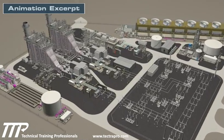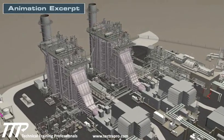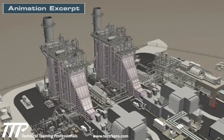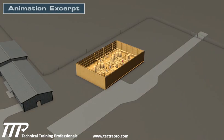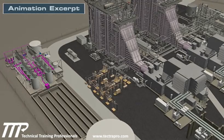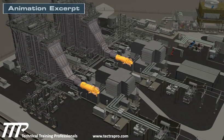The Plant 3 Power Center is a state-of-the-art facility that uses natural gas-fired gas turbines to generate electricity. To increase overall plant efficiency, the exhaust heat from the gas turbines is used to create steam in the heat recovery steam generators, or HRSGs. Natural gas from the local pipeline enters the facility through its compressor station, used to raise the pressure if necessary. The gas is further conditioned at the turbine gas skid, which provides heating and filtering. Each turbine will produce approximately 170 megawatts.